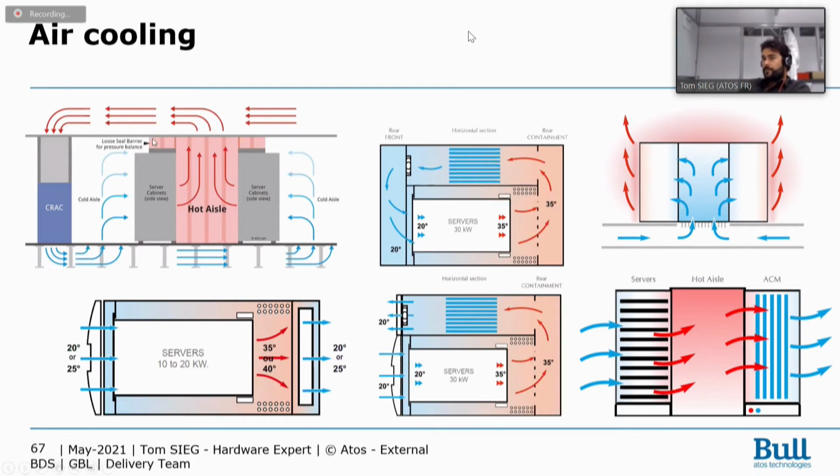You can lock your row with some plastic containers, some isolating little room inside your data center to prevent any air exchange between the hot and the cold row. Of course, leave a little seal just to prevent any overpressure problem.